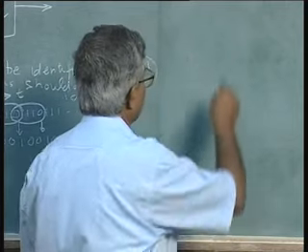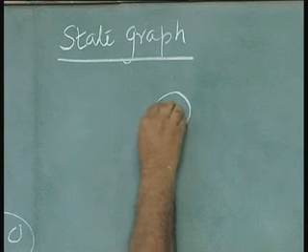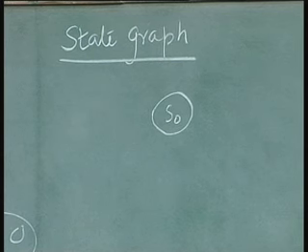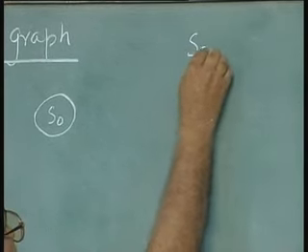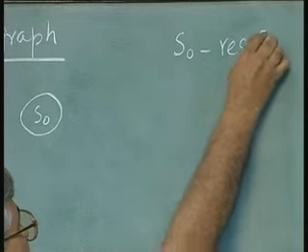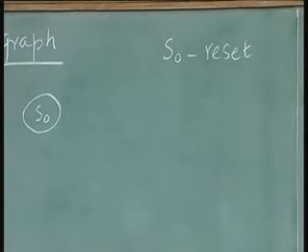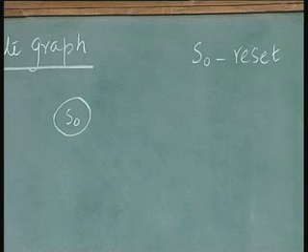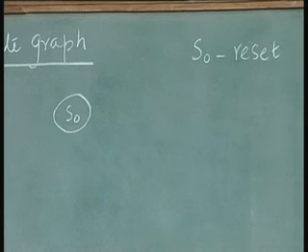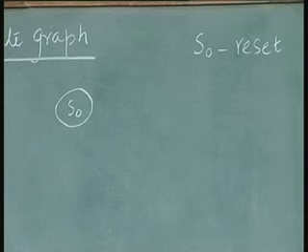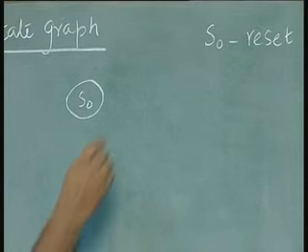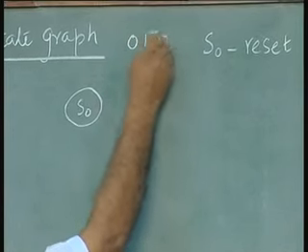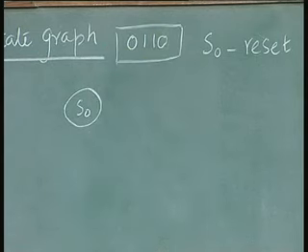I am going to directly start doing it. So let us assume the first, there is a state called S0, which is a reset state. As I said, you have to start with the reset state with output 0. So I will make a note here, S0 is reset state. Then in each state the input can be 1 or a 0, that is all. There is only one input, one output. So input is 1 or input is 0. If the input is 1, it does not even fit into my pattern. What is the pattern I am trying to identify? 0 1 1 0. Remember, this is the pattern I am trying to identify. If the very first bit is a 1, it does not fit into the pattern.